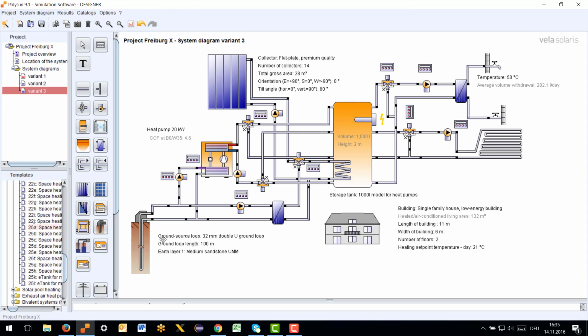This has different advantages and disadvantages. The advantages are that our collector will not go into stagnation. On the other side, we are not quite sure what happens here in the ground. If you have a single loop, the energy can simply disappear. If you have not just one drilling, but maybe 4 or 5, so you have a complete field, then you can store the energy over the year. So during summertime you will bring energy into the ground and you will get it back with the heat pump during winter time.